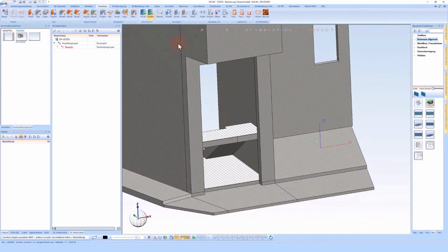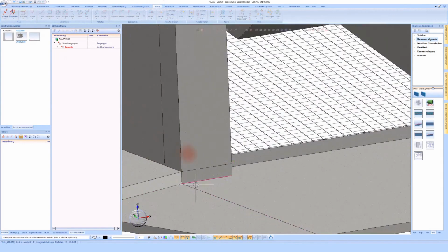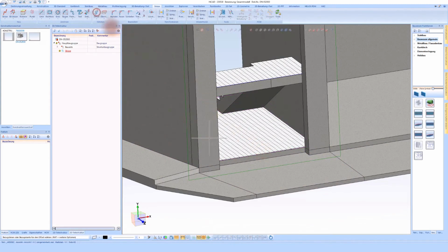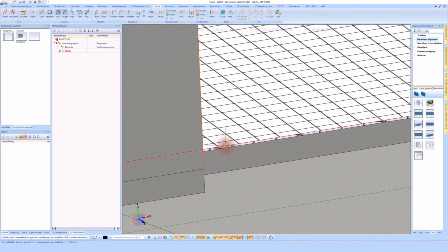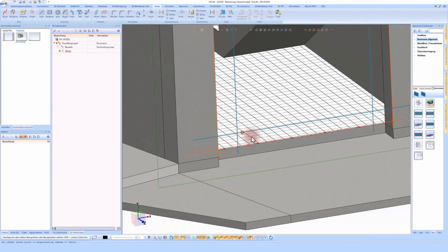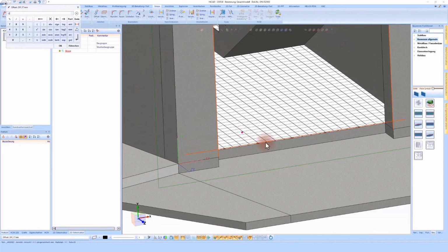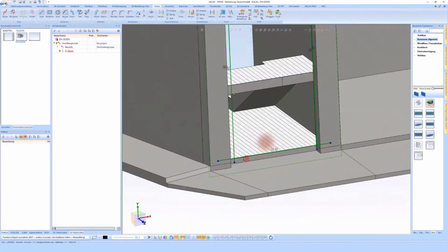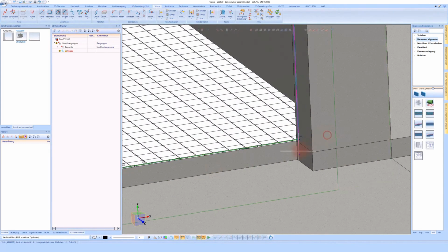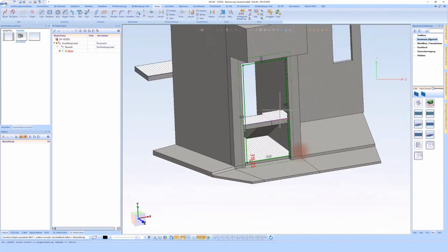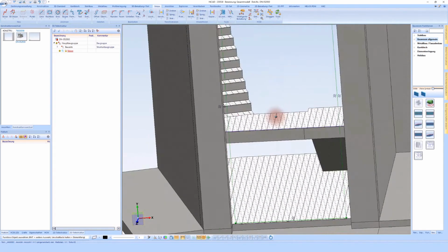That means the first step, I create a sketch where I place it on this plane. And in this case, I can select my edges with offset, for example, to define my boundary, I will simply set this 100 millimeters from the outside. And so I already have my first edges here. What I will do here is trim the corners. Of course, that means this will simply be my outer grid.